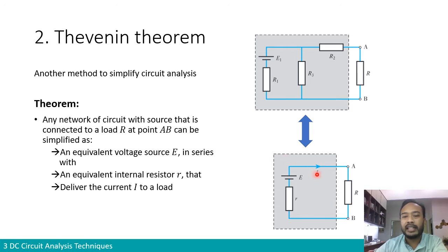Norton theorem is basically the same thing, but instead of having a voltage source, we can consider the whole circuit as a current source. So the voltage source here is a constant voltage source with an internal resistance that represents the whole network outside of this resistor load. So what does it say?